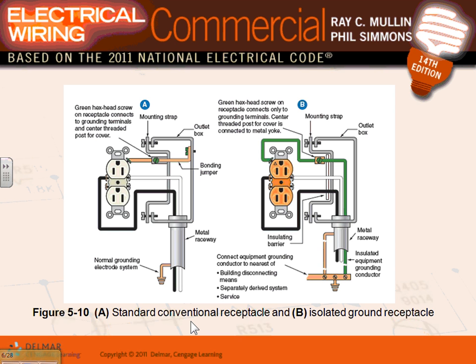Can you see these ears here? The grounding slot is completely isolated. When you put your isolated grounding conductor right in here, the only thing that's grounded in this receptacle is the slot. These ears are grounded through the frame of the box.